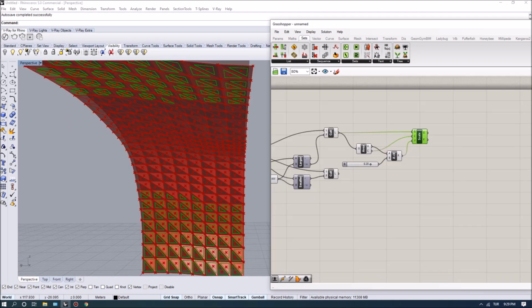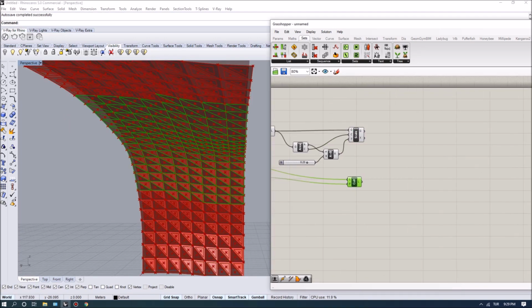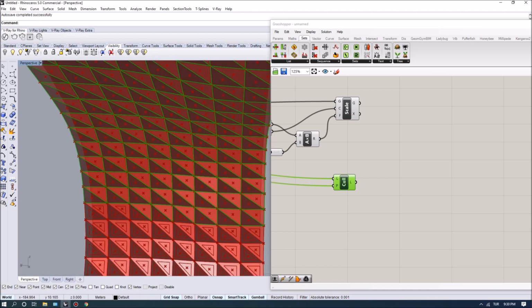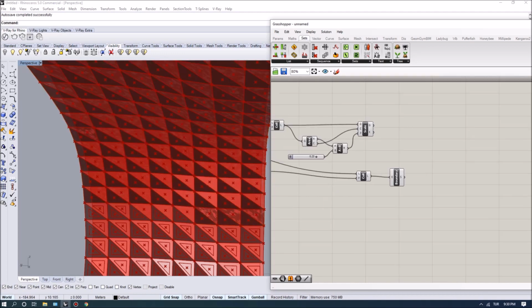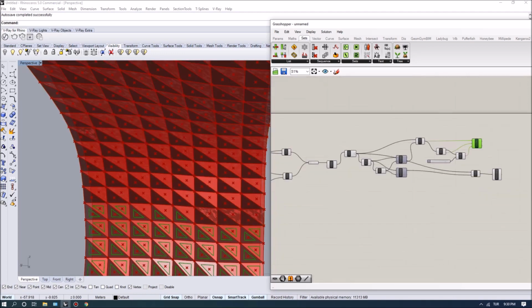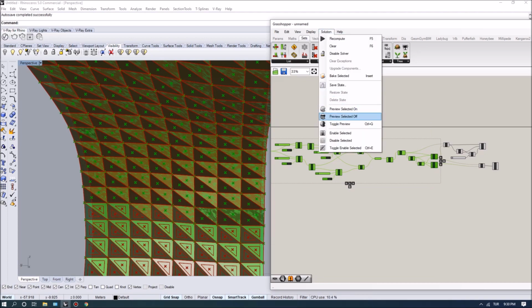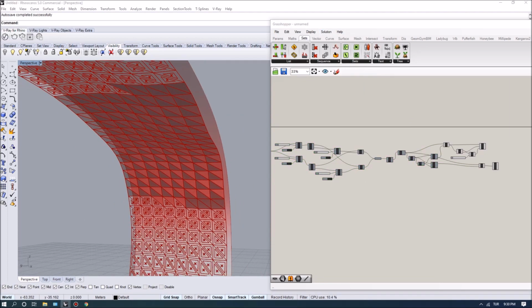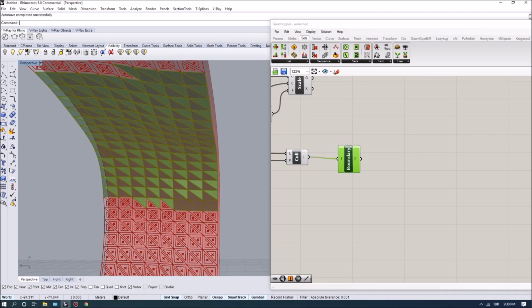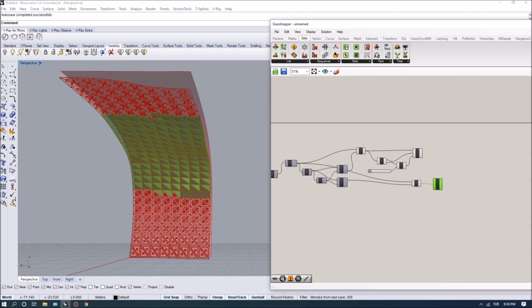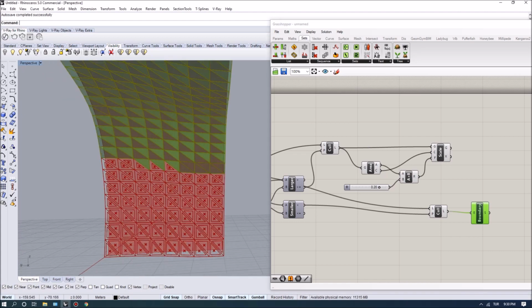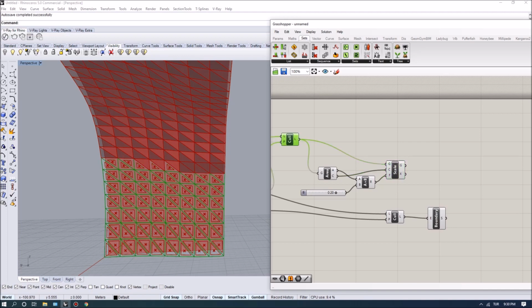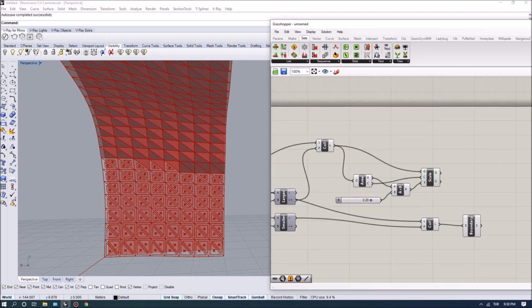And in the last step, what I want to do is turn these into panels themselves. So these boundaries, these pieces, we can simply turn them as boundary surfaces. But to turn this top row, let me actually hide everything before doing this. So this row, these triangles are already converted to surfaces. But to do that to the top part, we actually need to combine this data. So I need to associate each boundary with its scaled boundary, and we can do it by weaving the data.